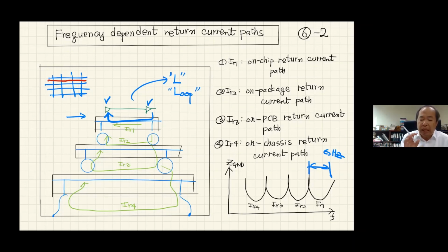But anyway, at really high frequencies, return current has to go through the on-chip digital ground. And usually that ground is in the form of a grid. So it will be very, very difficult to maintain 50 ohm. Because of design rules, we cannot cover the whole plane with metal inside the chip. That's why we are using the grid type of metal inside the chip. And in a certain way, the on-chip interconnection has certain resistance.